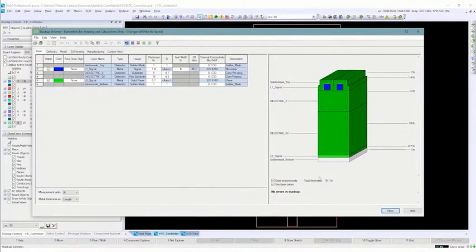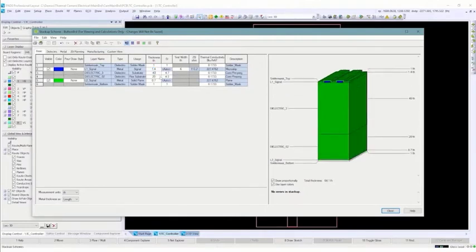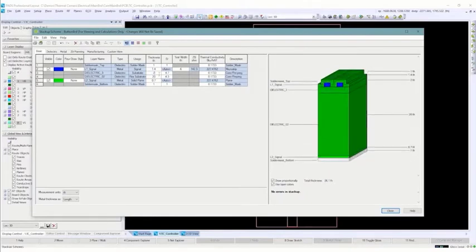And then this is where we can adjust the thickness of the board. So we're going to go ahead and make this, we'll just make it like 30 thousandths. The board doesn't need to be super thick by any means. We can adjust our solder mask layers, our copper weights if needed. I want the dielectric to be 30 actually, or 20. I want my flex material to be 2. All right, copper weight and so forth. All right, so there's our basic 2-layer board with our flex substrate that a copper trace will go on to.